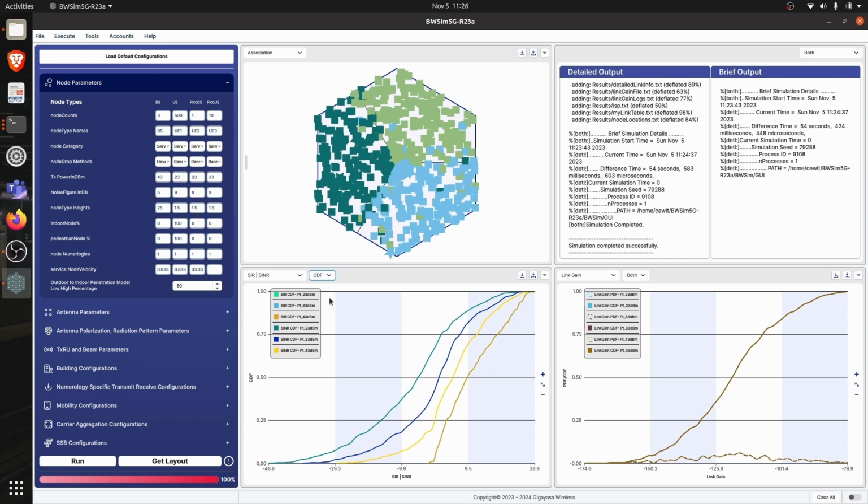Thereby, we are concluding the first observation with two sub observations, that is, when you increase the transmission power, the SIR remains the same and the SINR improves in a noise limited scenario. The second observation is that the SINR improves better in larger cells than in smaller cells.